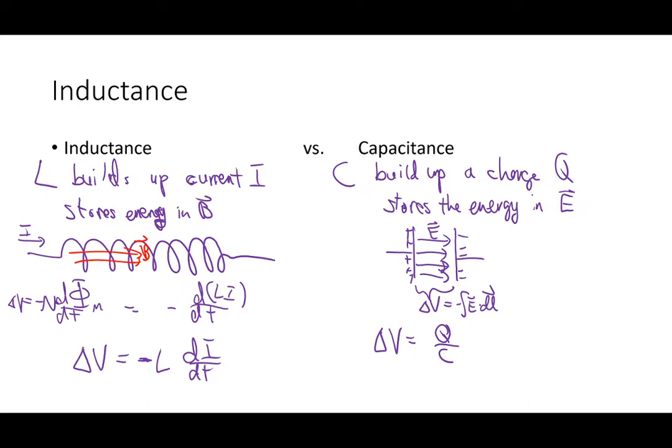So to relate these, and then just to take this one more step, yes, they both store energy, they store in different fields, but ultimately the governing equation is what's going to make all the difference here in terms of circuit analysis: this one uses the derivative of current, whereas this one uses charge, which is the time integral of the current. And that's going to be a very significant thing as we move forward to analyze these kinds of circuits, as well as even if we move on to AC. That's very, very key.